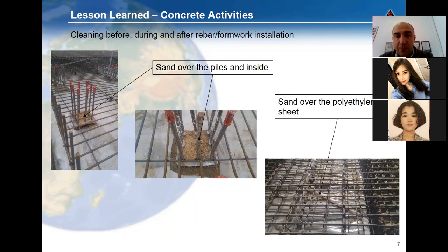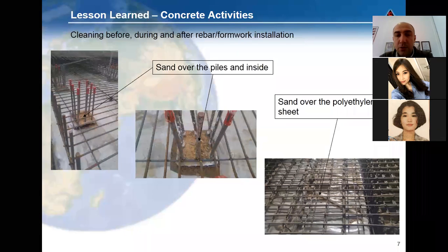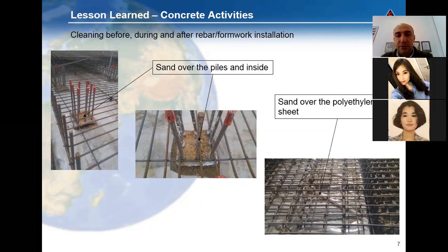Because if you apply the fresh concrete, it will not be connected with the steel and the lower ready construction, and will show not such good results as it would if there were cleaned surfaces and ready surfaces of the constructions located below.